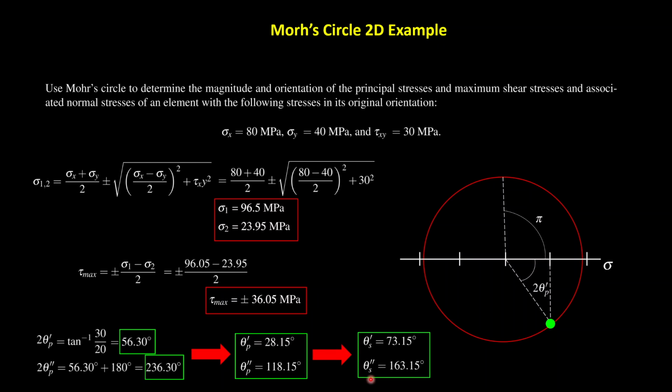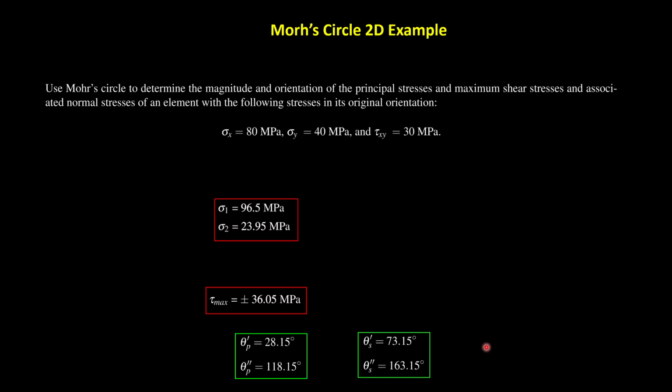So in this case, as I'm talking now in physical quantities, I already corrected this. If I add 45 degrees to this value, I will get the position of the maximum shear stress, and then the other axis where the negative shear stress is located is going to be at 45 degrees from this angle here. Great. Now we're approaching the final solution of this.